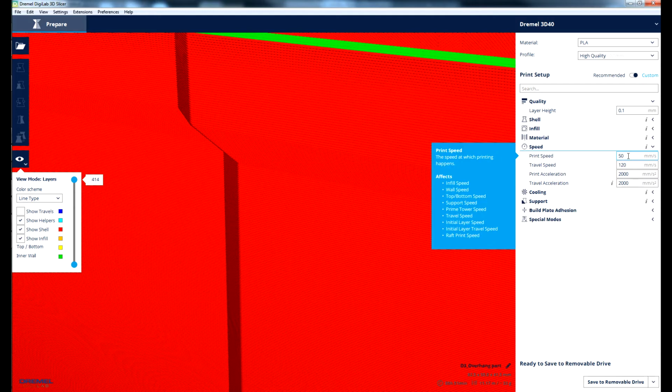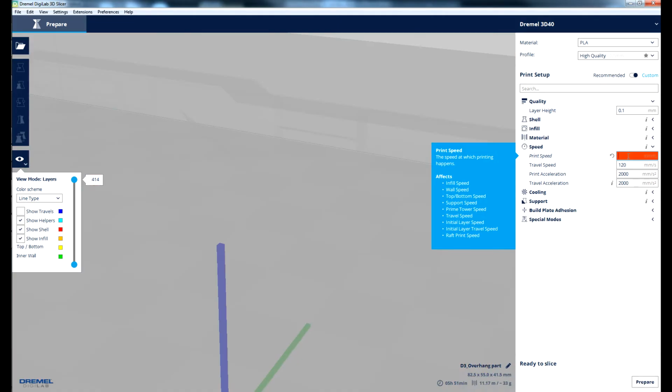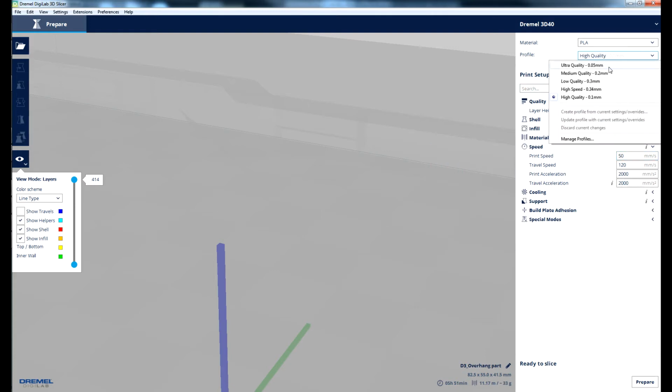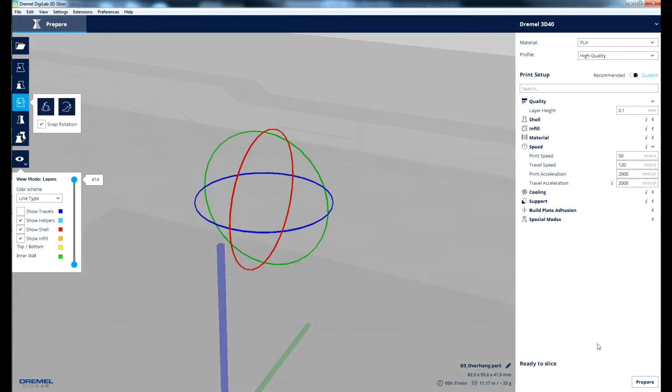Changing the print speed to a value faster than the recommended setting has a cascading effect on almost every variable related to a successful print. Changing the print speed is not recommended for beginners. Adjust your layer height or slice thickness if you need a faster print. The slicer preview or layer mode is a good way to illustrate this point between print qualities.